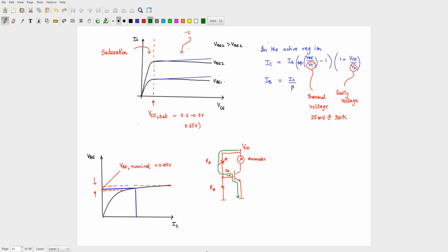In fact, for this particular thing, you do not even need this RB here. Yeah, we do not need this RB. Okay. Based on this analysis we did here, can you approximately at least write this VCC minus IB times RA, right, minus VBE.